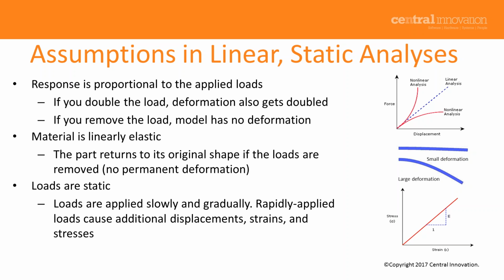First, let's look at the linear. We call a material linear if the response of the material to the force is linear. For instance, you can see there is a linear line here. When you are applying 1 Newton and your model is displaced by 1 millimeter, then you apply 2 Newton, it would be 2 millimeter. So that's what we call linear response. Any nonlinear material will respond as a curve. You can see 1 Newton, 1 millimeter, 2 Newton, maybe 10 millimeter.